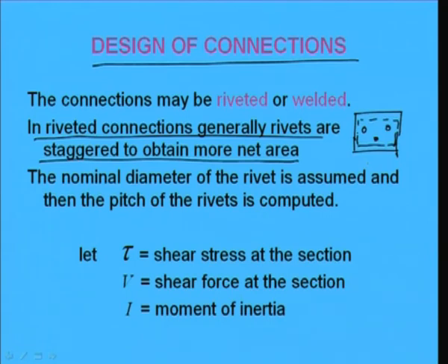So, in this case the failure will be either here or here or here, meaning we get only one hole. So, the net area will be more, otherwise the failure may happen like this, like this, like this, where the net effective area will be very less, since two holes are in the same line, right.